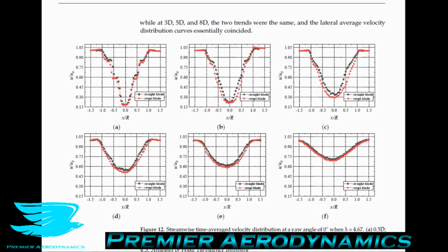That's an instrument that we make to accurately measure the density of the air that you're using. And this is important because the density of air changes between 2 to 4% every day. That's just due to changes in pressure, barometric pressure, and humidity. And between seasons and weeks, that does change even more, up to 10 or 15%. So if you are not measuring the density of air, it means that the velocity of your wind tunnel is not what you think it is.